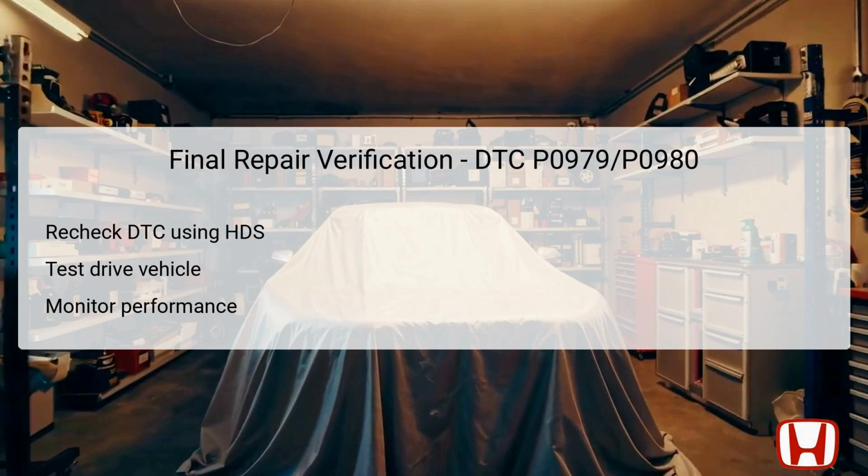After performing the necessary repairs for DTC P0979 and P0980, it's crucial to carry out a final verification of the repairs made. Begin by utilizing the Honda Diagnostic System, HDS, to check for the presence of any diagnostic trouble codes. Clear DTCs again if any remnants persist, and conduct a test drive to assess the vehicle's shifting performance.